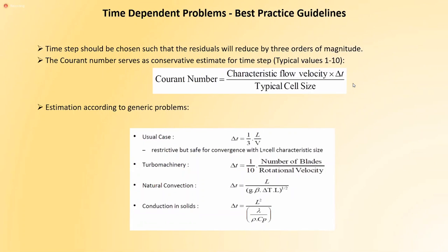In implicit schemes, it can be unconditionally stable, but if the cells are not refined enough and the phenomenon goes too fast through the cells, you just get a big error. So you won't get a divergence, but you get an error.